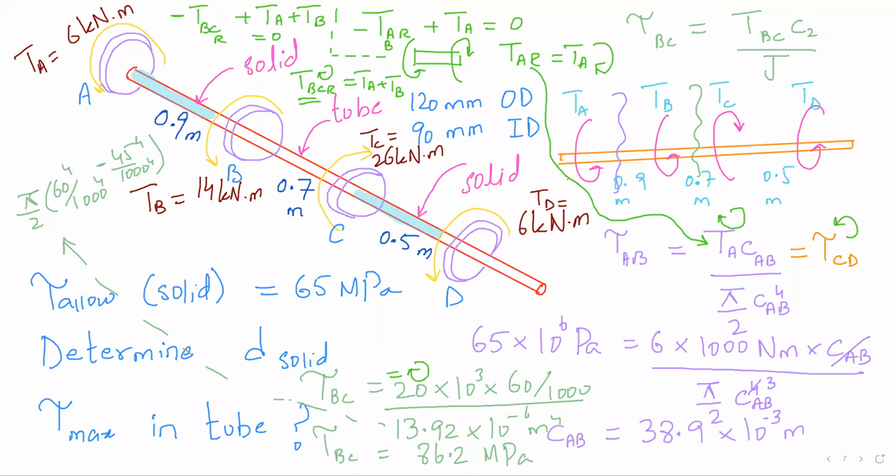So essentially you have torques, right? So technically these shafts are twisting, right? Do you remember any angle of twist formula that we went over in this class? TL over GJ, right? So just remember these formulas. Change in length is PL over EA. Twist is TL over GJ.